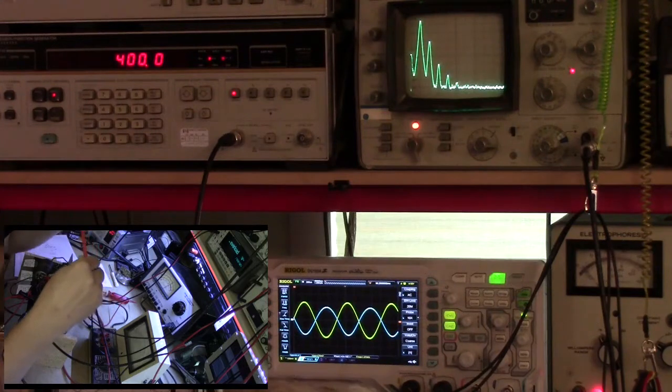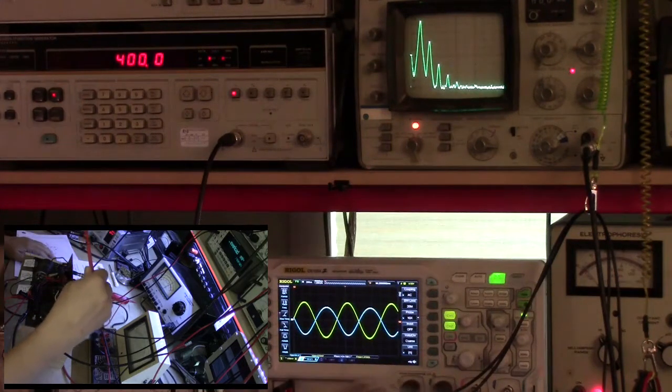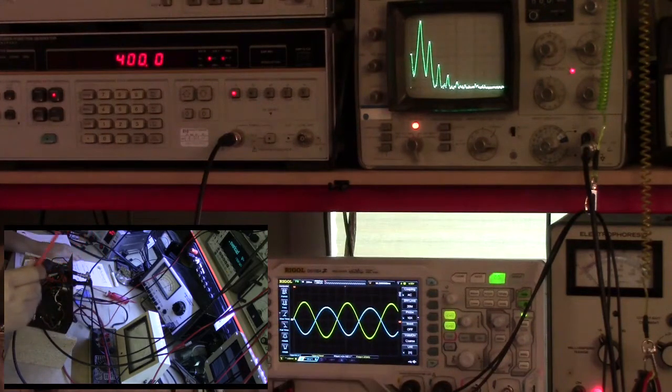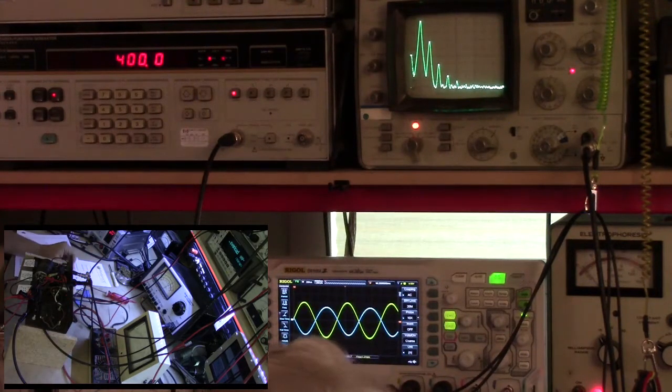When you get close to zero on the control grid, you're going to start seeing grid conduction. On a small signal Pentode like this, you don't want to drive the grid very positive, because the current flow out of the grid will cause it to heat up, and there'll be a little bit of power dissipation there. So we're going to stick to voltages less than 1.2.